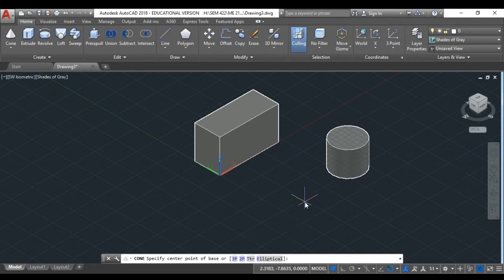This time, guys, instead of putting the center here or there randomly, I decided to put it on the top of that box. How can we do this? Very simple, guys. If you recall, usually we used to do what's called object snap in the two-dimensional. Here in this case, we have two kinds of object snap. There is an object snap down there, which is that icon. You see this icon? This is for two-dimensional. And there is another cube for the object snap of the 3D objects.